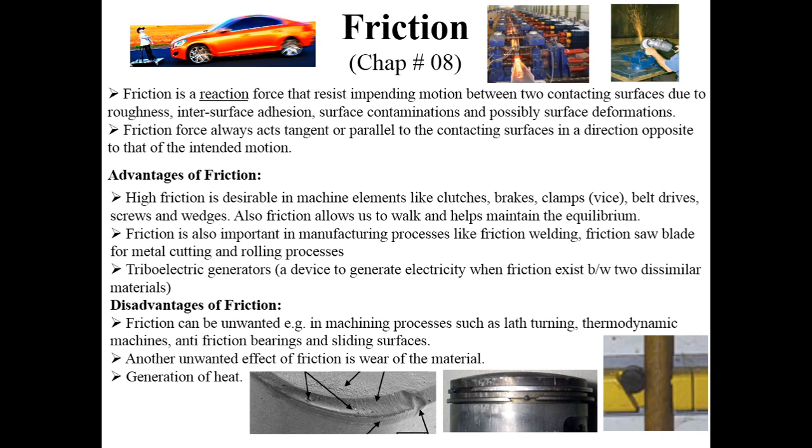So they work on the principle of Newton's third law. As soon as you remove the external loading, you will see that these reaction forces and moments vanish. But they are very important concepts in statics because they are able to keep your body in equilibrium, and they allow certain degrees of freedom while blocking others.